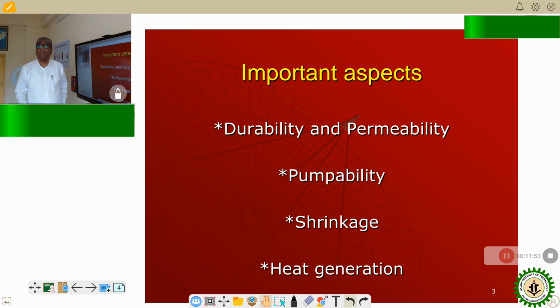Now, the question is that when you are pumping, obviously there is something with the pump also. You have to pump at a particular pressure. Now, unless you use viscosity modifying admixtures and control the pumping pressure, what will happen is that at the top, maybe slurry will come out first, then sand will come out, then chips will come out, and the whole thing will be a mess.